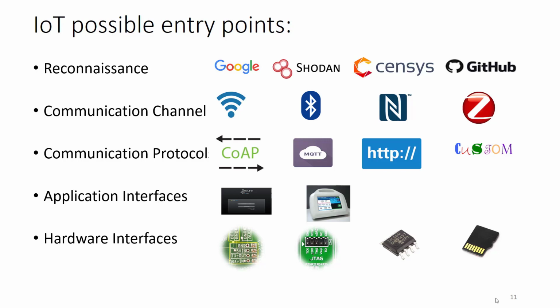Apart from the communication channels of hardware, there are low density storage memories available in the devices, that is either an SD card or EEPROM as we mentioned, and also flash ROM, and sometimes the microcontroller unit's memory area. Also, a very important thing which we look for in IoT devices is the firmware of the device.